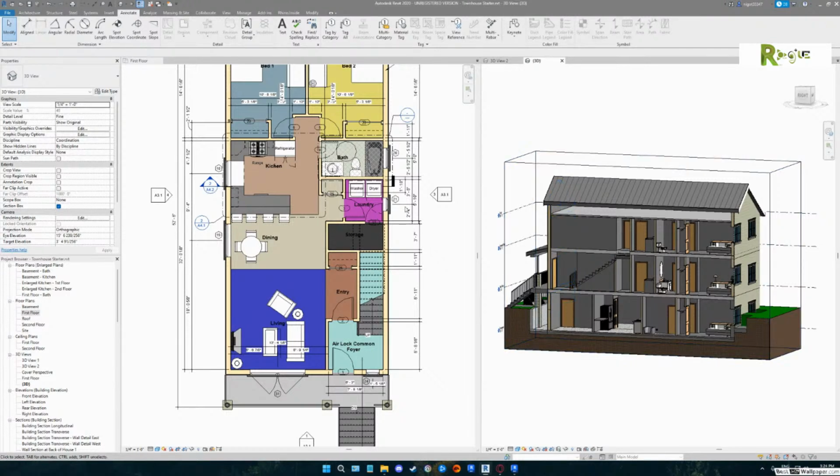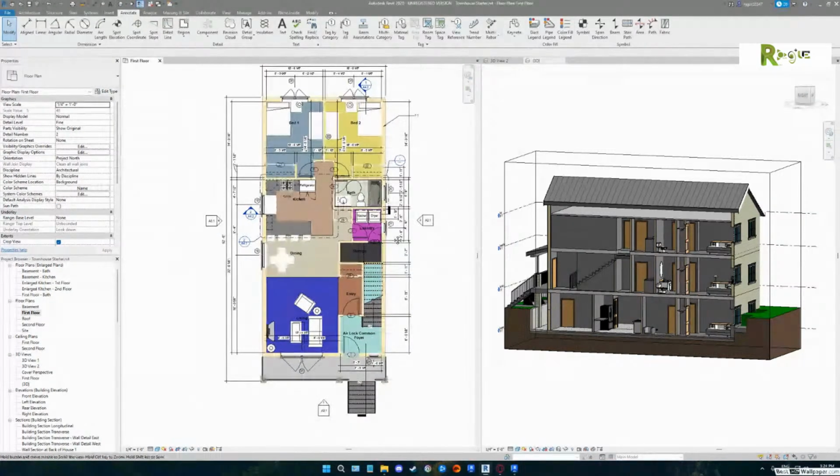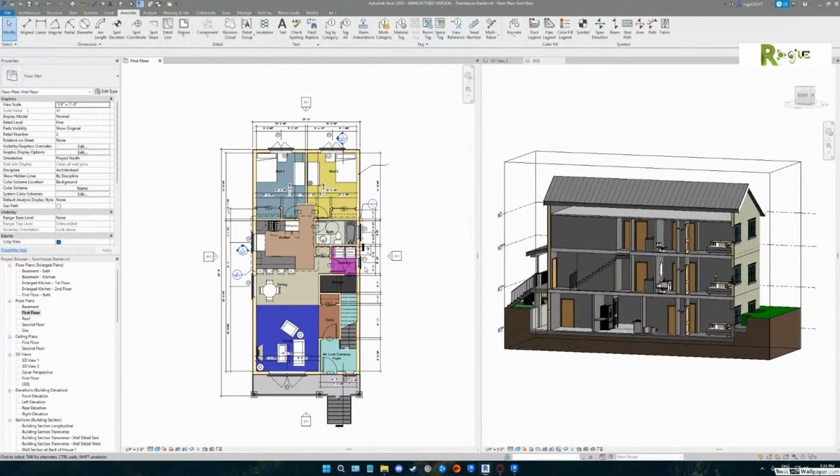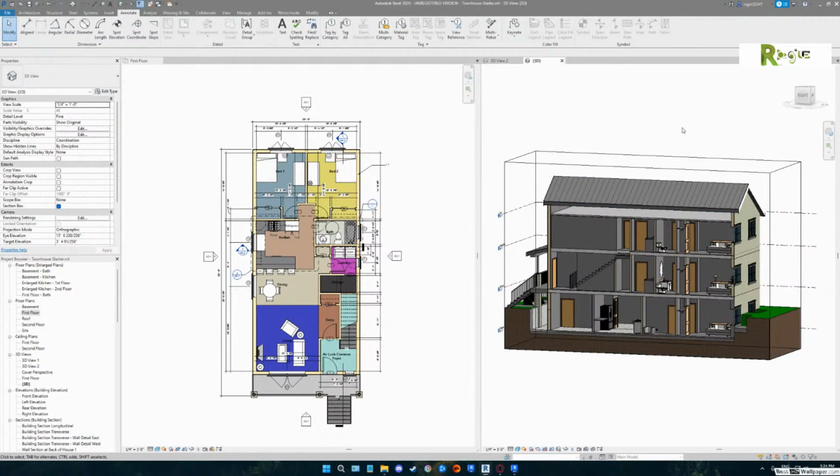Can we go over the tags that you said? There was a way to make them. I definitely don't think I did them the correct way. Well, there is no real incorrect way to do them, but you're probably using all category tags right now. And the trick is to use some category tags, some material tags, and some multi-category tags. And then also to use multiple types of tags as well. So multiple door tags, multiple pipe tags, multiple duct tags.